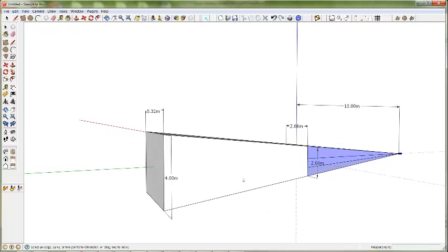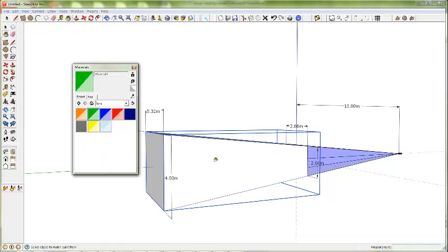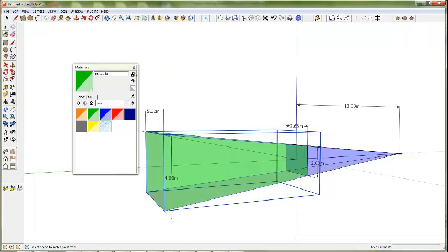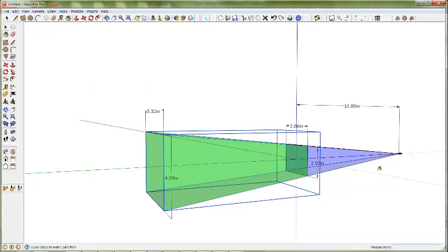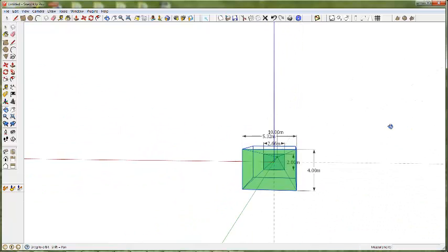Now I'm going to select my paint tool, and as we discussed earlier, I'm going to select green for this next segment, which will represent the recognize area, where at the 20-meter position, the doubling position out there from the standoff, the field of view now is 4 meters in the vertical, which is double what it was at the 10-meter position. So a person would be about 50% of the field of view at that point. And at that point is where an operator should be able to recognize an individual.